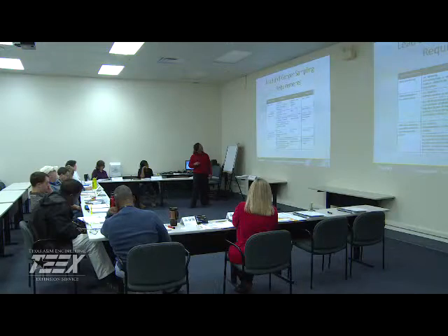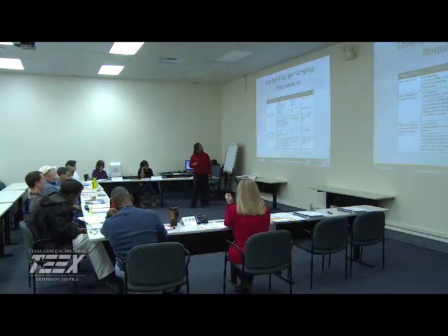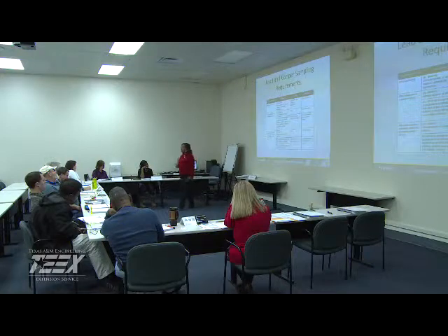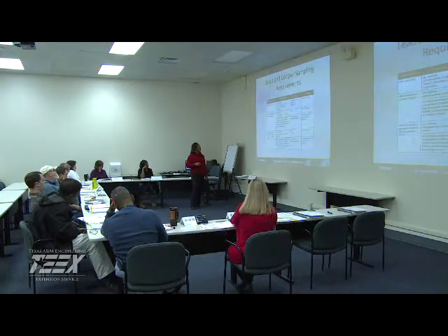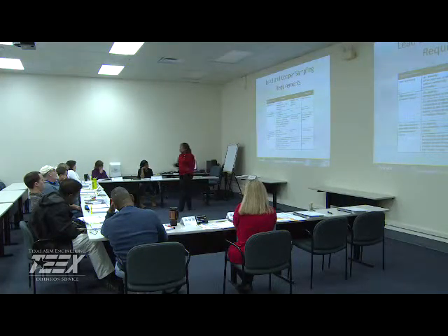After installation of corrosion control, pH, alkalinity, orthophosphate, silica as applicable at your taps every 6 months. pH, alkalinity, dosage rate and concentration, if it's adjusted as part of controlling the corrosion, and the inhibitor dosage rate and the inhibitor residual you may be using at the entry point to the distribution system. And again, you're looking at that almost every 2 weeks, if not more often.